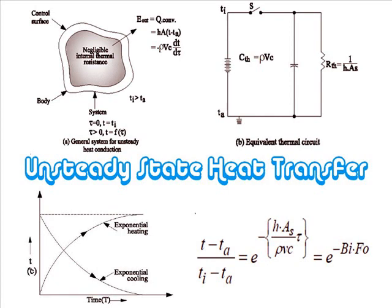So friends, in the present video, we are going to discuss transient or unsteady state heat transfer. This is a continuation of conduction heat transfer. In this video, we are going to discuss unsteady state heat transfer, different examples related to transient heat transfer, and the lump parameter approach for analysis of unsteady state heat transfer.